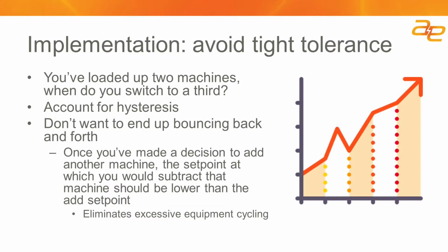By knowing the input, you need to understand at the end of the day the cost for producing that utility. Without measuring the fuel consumption, whether natural gas or fuel oil, you'll have a hard time quantifying and determining how to configure and prioritize your control scheme in the absence of that measurement.